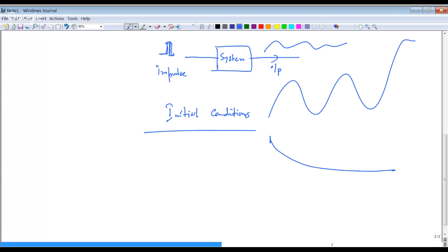Because the output of the system can become, depending upon if the system, for example, is critical, that depends on natural vibrations in the modes of the system, right? So if the system modes are linear or stable, then you can expect that the impulse response of the system is stable. It's BIBO stable. So if the poles of the system get perturbed, and if the modes are unstable, then any other input can give you a blown up output.